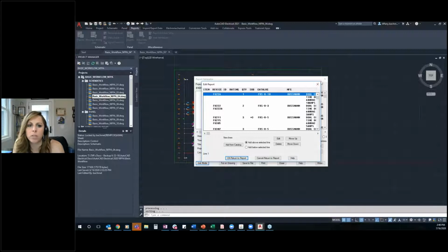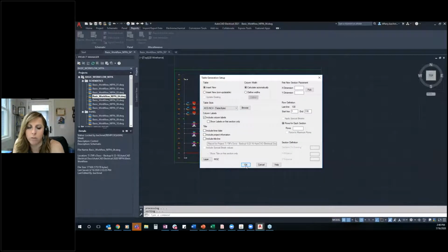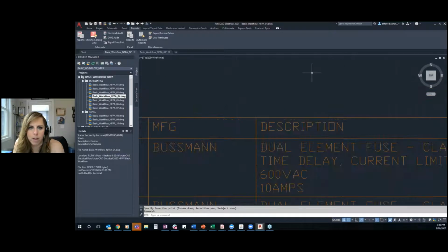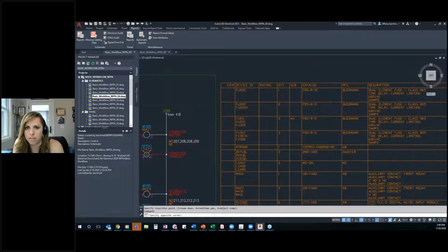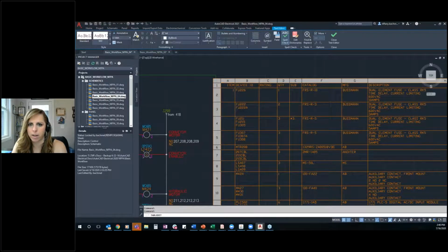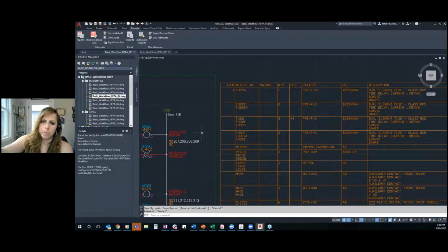You can also, once you place it, for instance, if I were to put this on a drawing, or even if you send it to an Excel sheet, you could manually edit it in Excel. But if I were to put it on a drawing, the beautiful part about the way AutoCAD tables work is they work just like Excel does. So I could come in here and type what I wanted, and I could put one in here, and I could even do the drag and drop of the diamond, and I could either have it duplicate like you're seeing it say it wants to do, or I could have it increase, just like in Excel where you could have it say 1, 2, 3, 4, 5, 6, 7, 8, 9, 10.